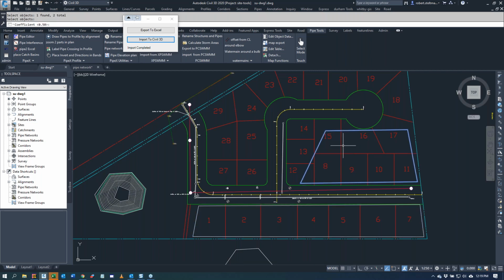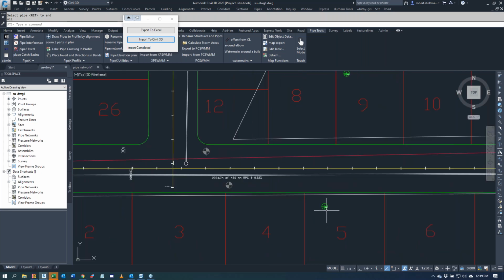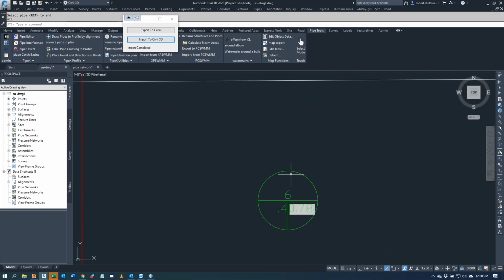It highlights the first one, runoff coefficient might be 0.5, it places a block. The next one, the runoff coefficient might be 0.4. We place the block that's highlighted with that one, and we go enter, and now it's associated with it. What the routine does is put an area number, the runoff coefficient, and the area. Should the polyline change, that area will update with it.